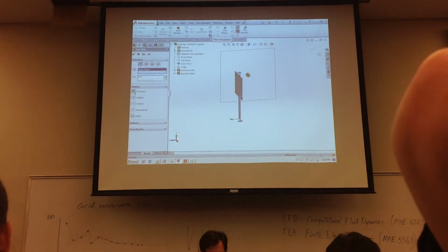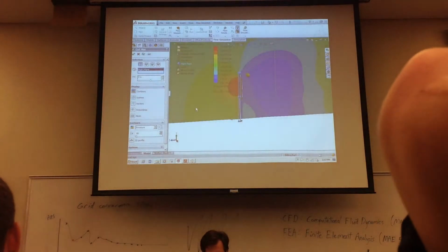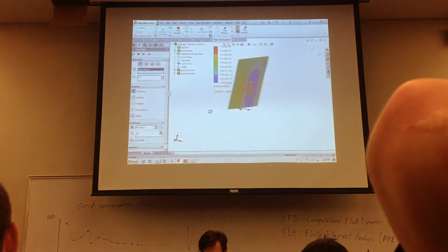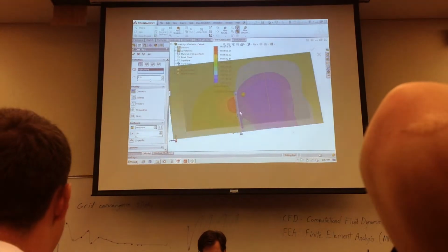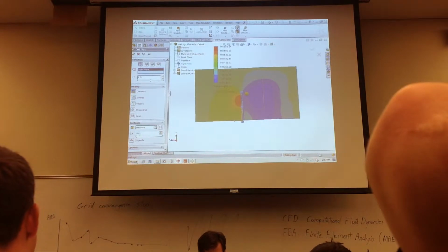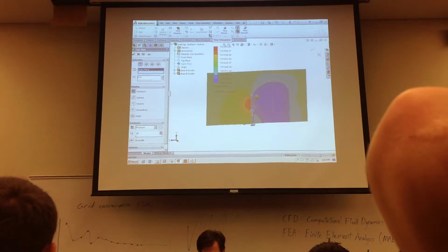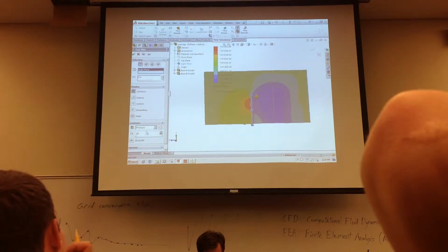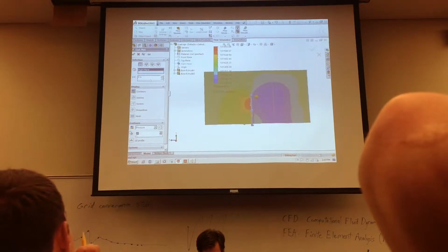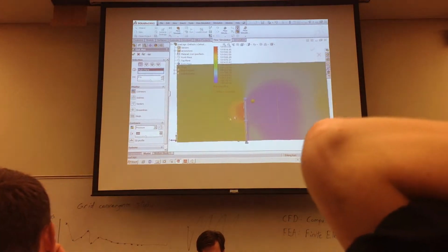Display contours that represent pressure. So let's turn on a preview here. Okay, so you see we've sliced through the computational domain, and here's what the pressure contours look like. Now this is only 10 different levels, so we can do better. Let's make it 100 levels for the pressure contours, so we get a much smoother looking plot, instead of something that's real segmented and chunky.